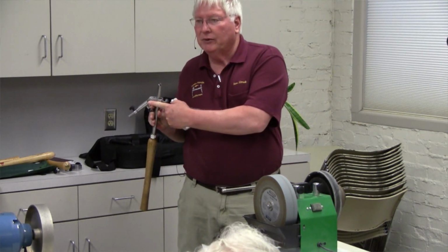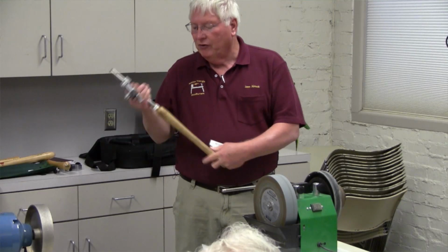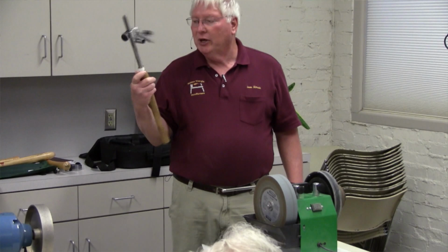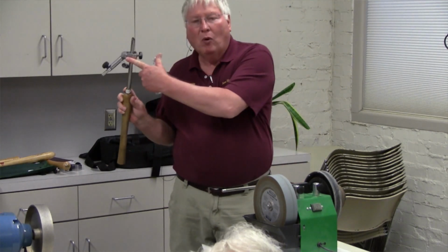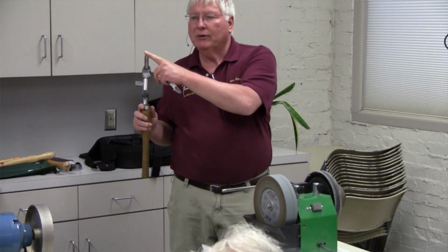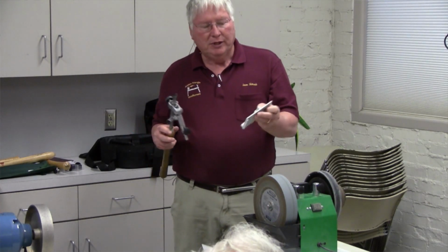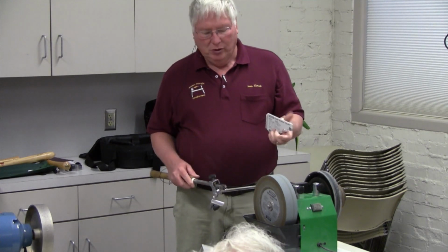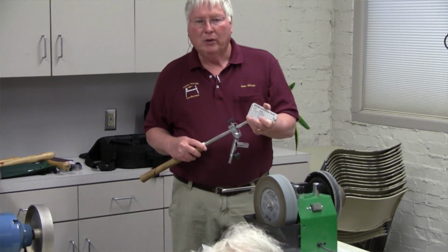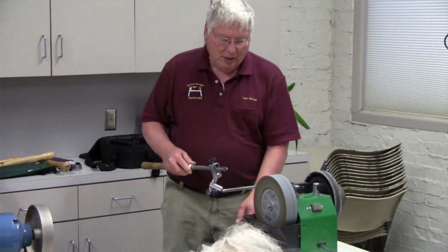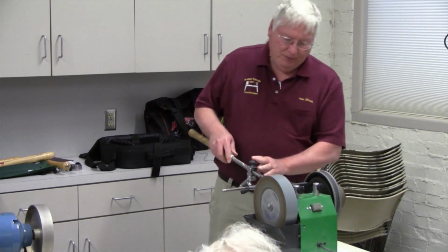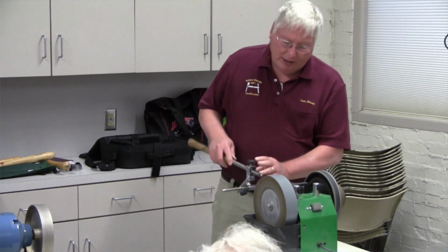The angle is marked here, and if you'll note on the tools, I've got a series of numbers and letters along the side, which tells me that I want to use number 4 on the angle here. I want the tool to extend out 65 millimeters, and I want the distance from the wheel to the bar here, using the A hole to set that distance. And then as the tool sits in, again, I've blackened the edge.